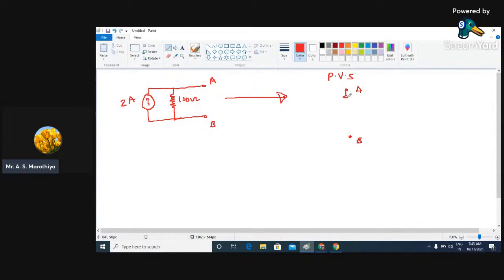So here we need to have a resistor, and then we need to take this. Now because the arrow is in the upward direction, which is connected to terminal A, and the down portion is connected to terminal B, that's why nearer to terminal A we need to indicate positive polarity, and near to terminal B, because the arrow is not available over here, it is supposed to be the lower portion, that's why here we need to take this as negative. I hope this point is clear.